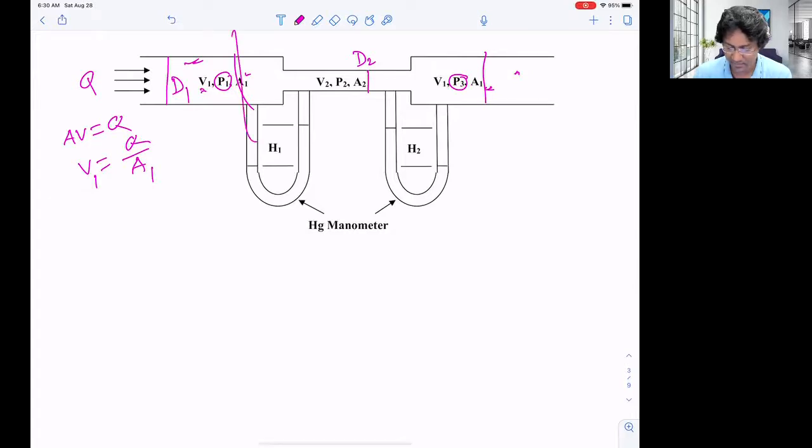So that setup is not 1 meter or 2 meters, but in our previous experiment when we calculated the head loss because of roughness or friction, we considered 1 meter of pipe length. But for this case we are not going to consider that. It will be only a few inches or a few centimeters. That's why we're not considering any significant length of pipe, and we are omitting the calculation of major loss. We are not going to calculate that again, because we know how to calculate it if you know the roughness and other parameters of the pipe.